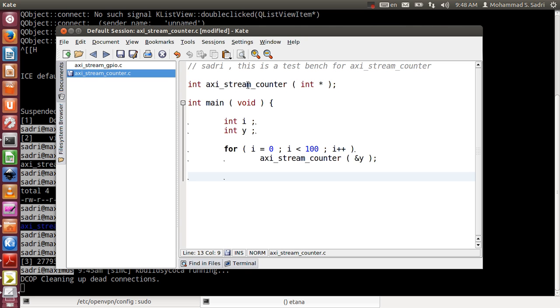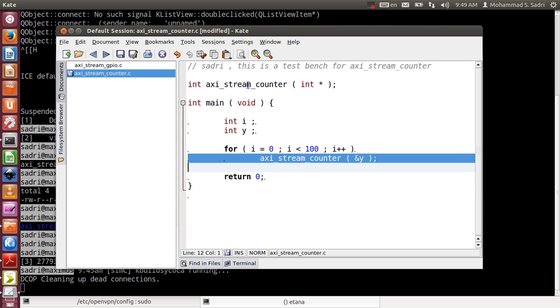For the main, Vivado HLS checks the output of the main function when it performs simulation. If the output is 0, it means that the simulation is executed fine and the outputs of this function match the outputs that we generate ourselves through the test bench.